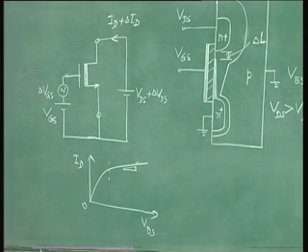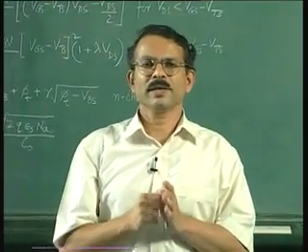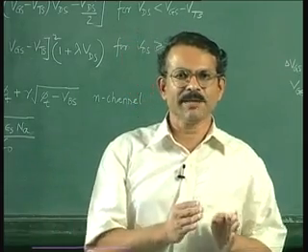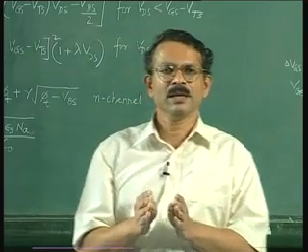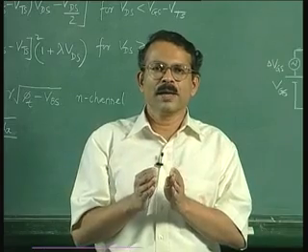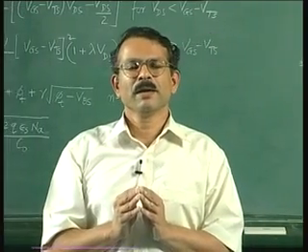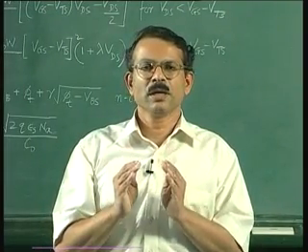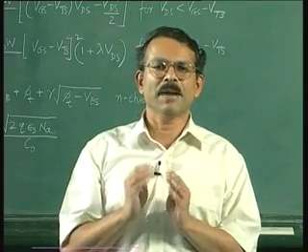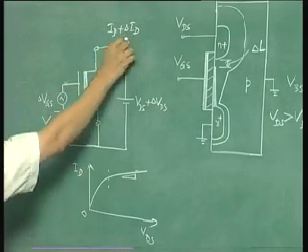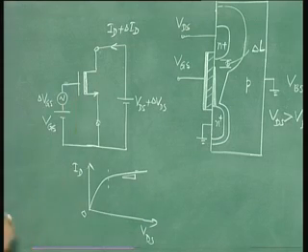Now another point to note is that the equivalent circuit is normally shown for the device working in the active region. So the bipolar junction transistor equivalent circuit was also applicable in the active region. So here in the MOSFET also this condition always holds. Okay. So the small signal equivalent circuit is shown or is used in the active region when the device works as an amplifier. Now the change in ID because of a change in VGS gives rise to a transconductance. That is why between drain and source you have a transconductance.